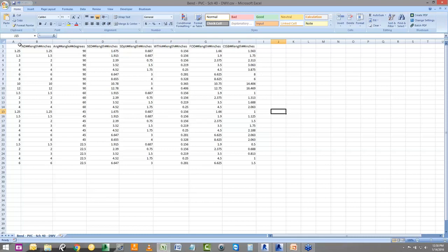This first column here, this A column, this is just for you to organize your information. Revit is not going to read this column whatsoever. It is, however, going to read this nominal diameter column. And this nominal diameter column is going to drive its ability to create anything. Say, for example, I were to go ahead and erase, well, I got a couple 1.5s here, so let's go to 1.5s, take all these 1.5s here, and I'm going to delete all of them.